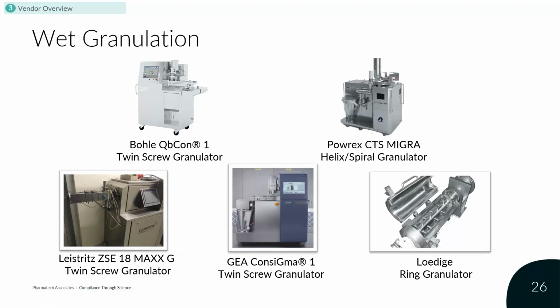If you select this kind of equipment, you have to look into, first of all, the ability of self-emptying, I would call it. So how good is this equipment at emptying after you switch off the process? What about the flexibility of the screw geometries? What is the outer to inner diameter? What is the torque capability of this kind of device? And how is the bearing of the screws, so that you make sure these elements are not touching one another?